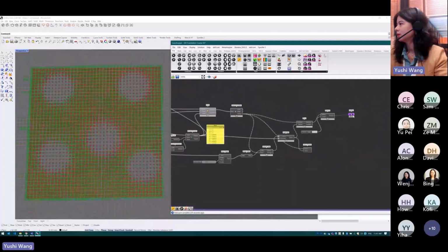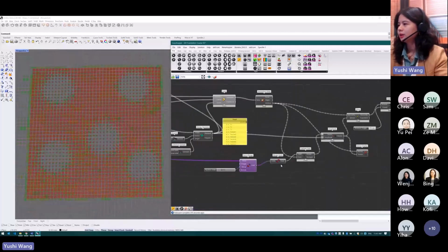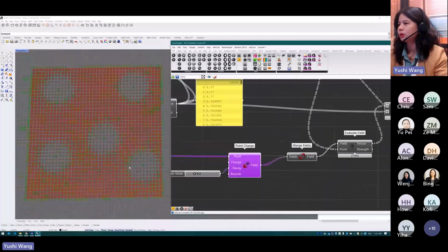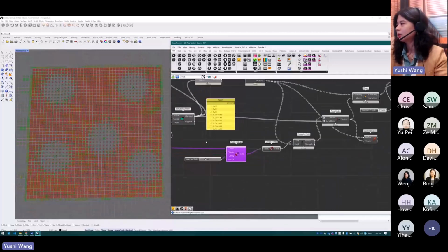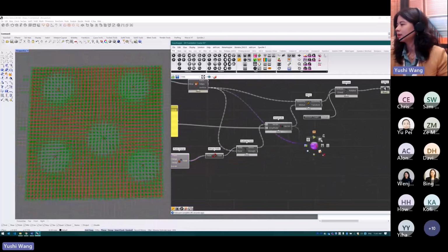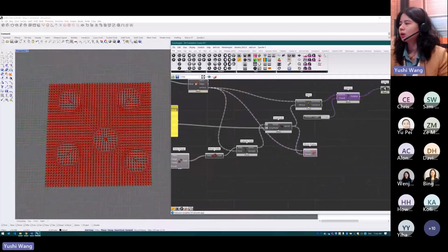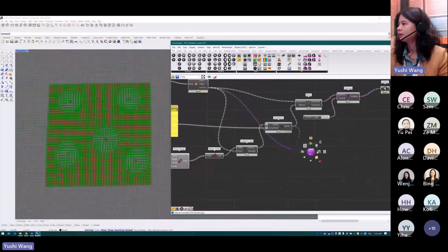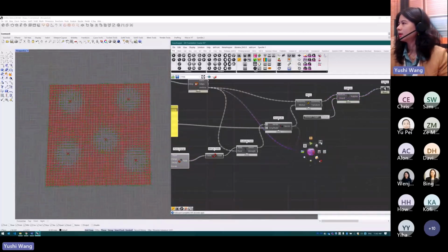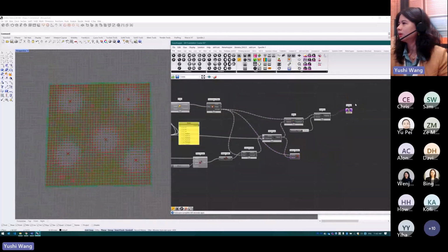Okay, let's add a charge to those points. We add a force field to each of those points. So we could see with the vectors that it looks like this. It's shooting out from the center point to the outside, and we use the polyline to redraw the new outline of it. So hide this, and we show the final result.